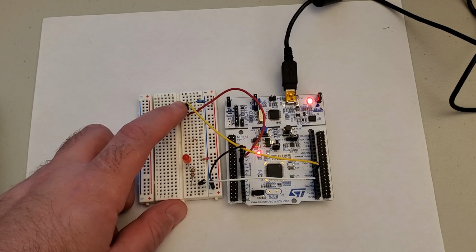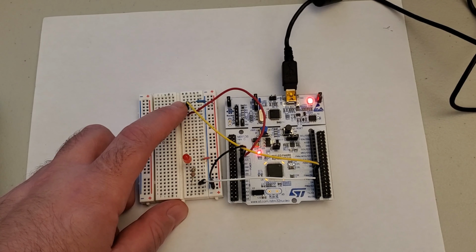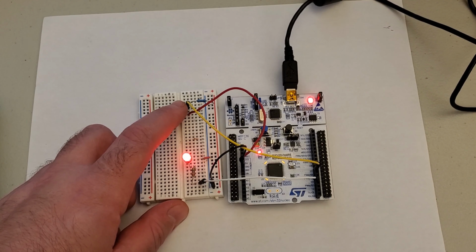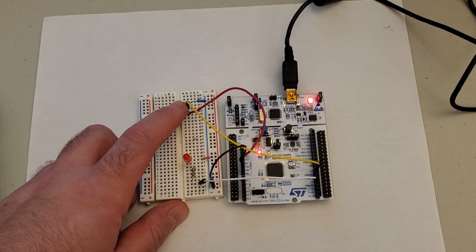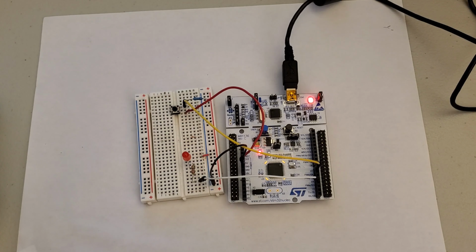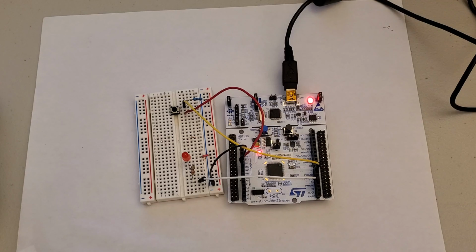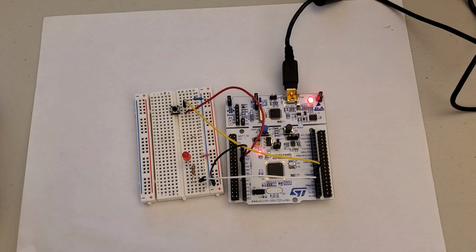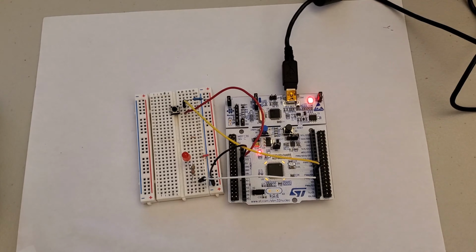Interrupts are very important components of microcontrollers which enable us to temporarily interrupt the code that is currently running and to run another function or a piece of code that can handle an external event. For example, in mechatronics and control systems, interrupts can be used to read and process encoder pulse readings.